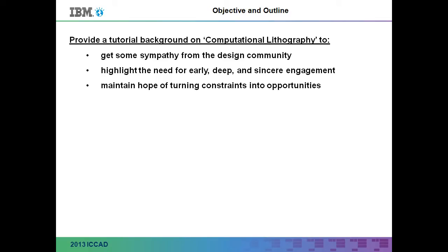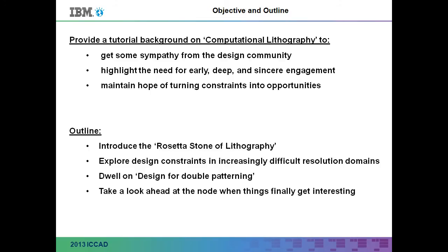Joel and I were talking about transistors. You go from the good old days where you had an infinite variety of transistors in width and length, and now we're down to maybe one, maybe two channel lengths. If you really beg, you get maybe a 2-fin device and a 3-fin device, and that's the entire spectrum of transistors you have. Maybe there's some opportunity to fundamentally improve how you approach design and not just treat it as a restriction. So as we go through all this material, maybe that'll spark some creative thought, and please put me on as a co-author in whatever patents you file as a result of this presentation.